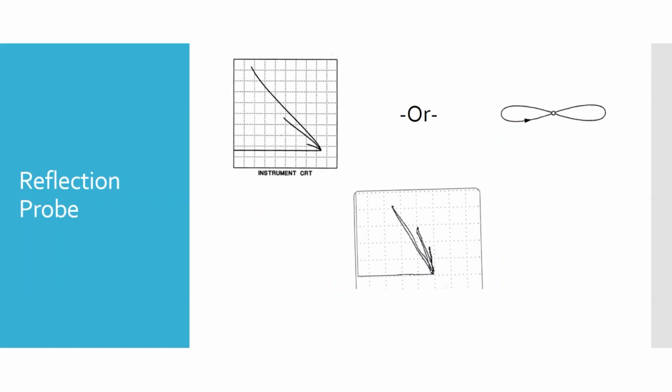So that's that. That is your liftoff, which we typically want to make horizontal if possible. So here, what they've done is gotten a liftoff, set the probe on the part, and then cleared the screen before doing the inspection. Now you can clear the screen at any point, but remember, this is a graph essentially over time of the inductive reactance of the coil.